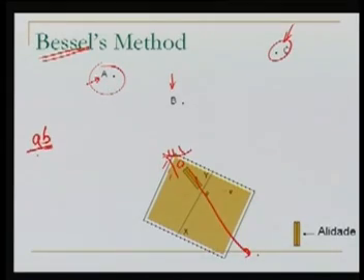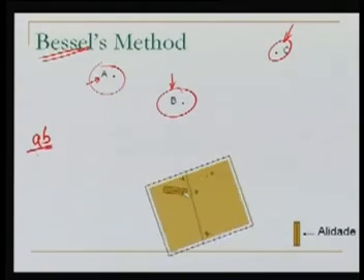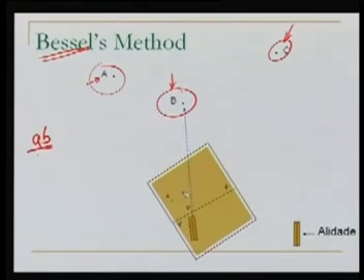We unclamp the table, and now we rotate the table along with the alidade so that B is bisected. Well, let us do that. If we do it, the table will rotate like this and B is being bisected. Again we clamp the table. So the table is clamped now.